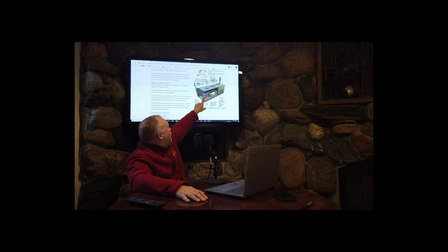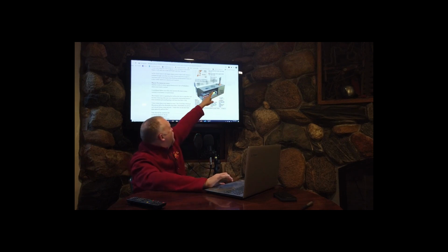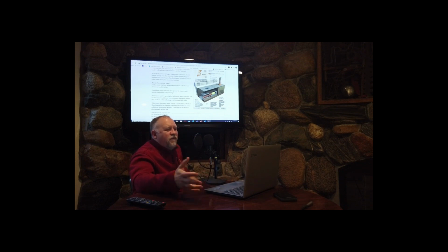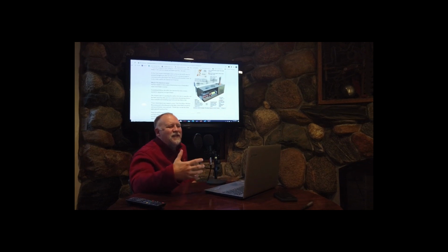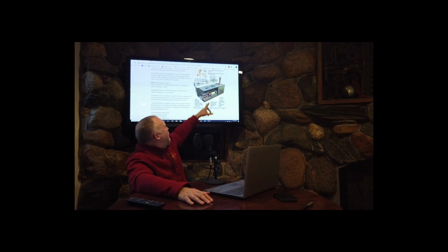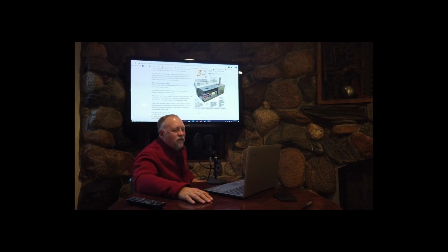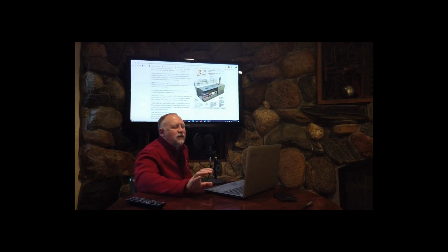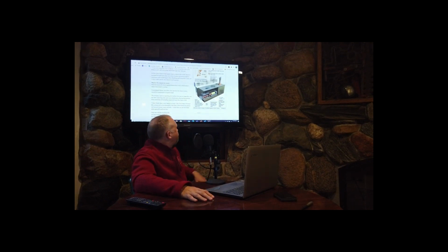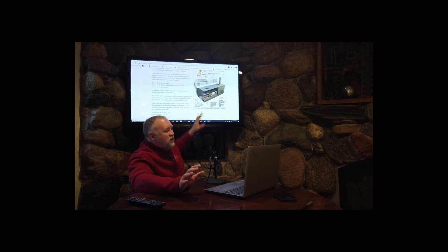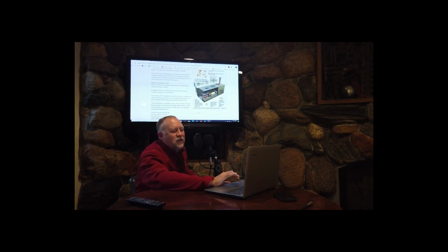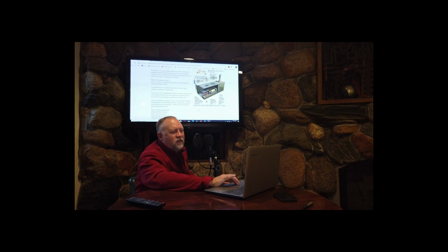All right, so buried down somewhere between 4 and 15 feet below the sidewalk and below the street are these steam mains. See that little orange cone? That's where the steam vents, excess steam that accidentally gets out, is going to be vented that way up above the windshield height of cars, so it doesn't obscure people's vision. All right. Now, periodically there'll be valves so that the workers can isolate different sections. Now, understand the potential energy in this.